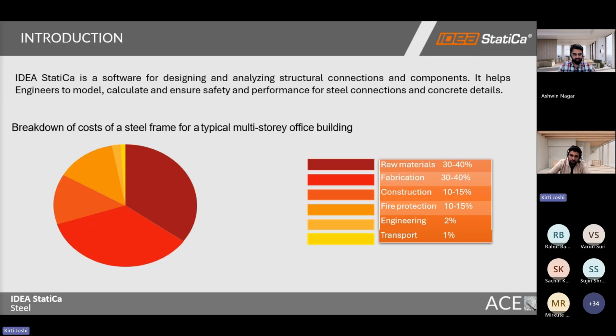So basically, it is used for both steel and concrete design, where you can do the connection design and also the member design in the steel structure, whereas you can do the wall design or the cross section design and the concrete details and see the concrete workflows in the concrete structure. So it is a huge database of the pre-designed 2D and 3D connections, footings of the CSS or the SSS connections, and also the steel to timber connections, which will definitely save the connection design time.